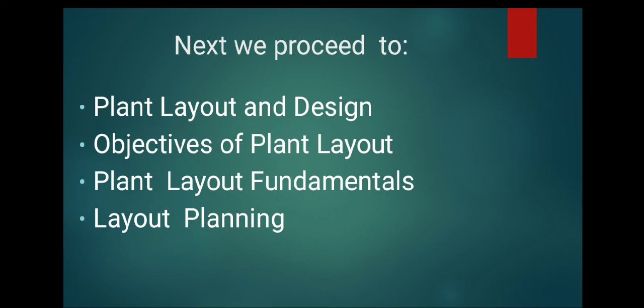Expansion, so easy to expand. Flexibility, easy to rearrange. Versatility, readily adaptable to changes in products, sales requirements, and process improvements. Second is regularity, a regular arrangement of the divisions of areas relative to size, especially when separated by buildings, walls, and floors, and also closeness, a minimum distance for moving materials and supporting services to the people.